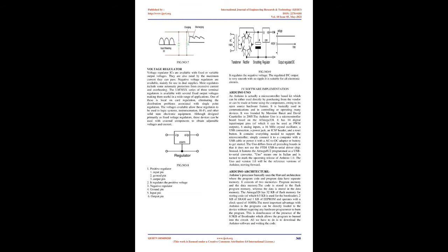Of course, even though the reservoir capacitor has large value, it discharges as it supplies the load, and its voltage falls, but not by very much. At some point during the next cycle of the mains input, the rectifier input voltage rises above the voltage on the partly discharged capacitor and the reservoir is recharged to the peak value VPK again.